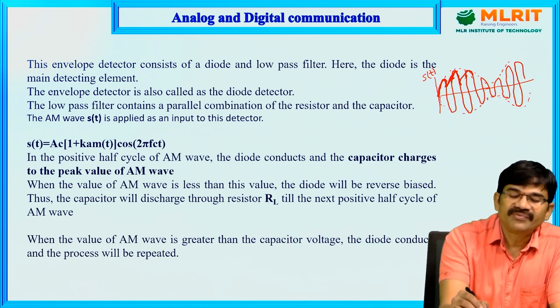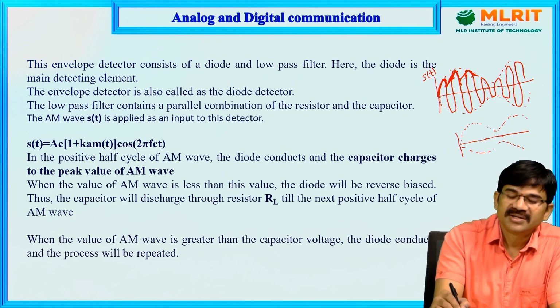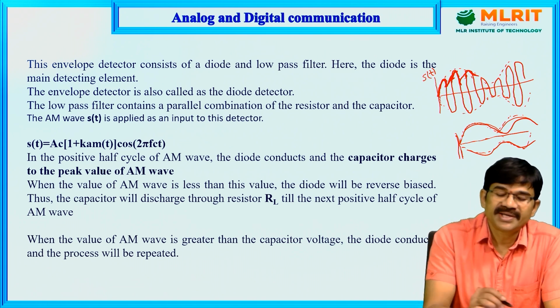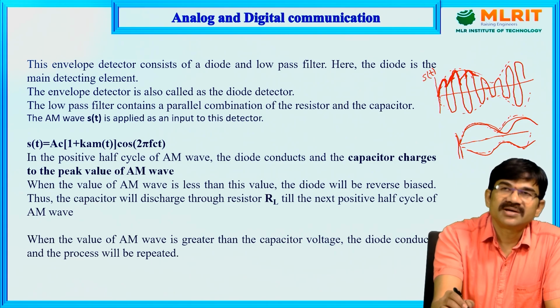The output waveform we obtain is the envelope of the signal, where the original information is concentrated. This is the demodulated output across the amplitude modulated wave, the sinusoidal signal we transmitted from the transmitter side, with the envelope following the sinusoidal nature of the signal.